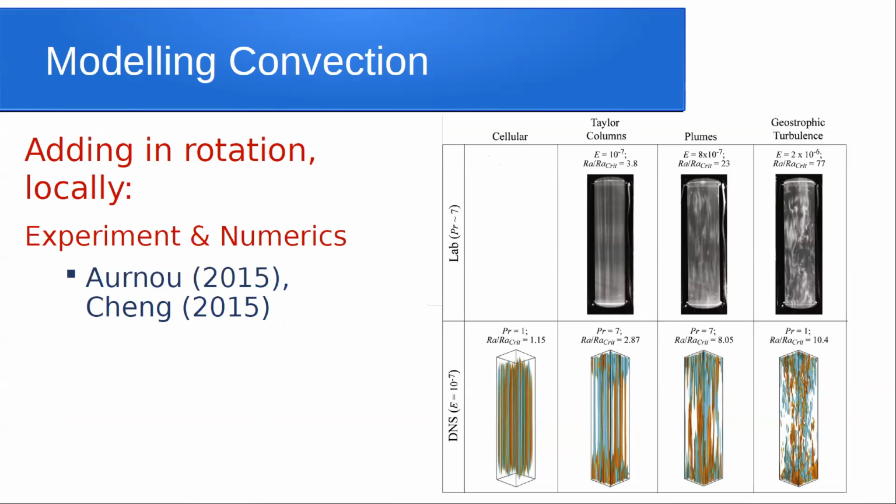So we're talking about Rayleigh-Benard convection in a box so far. What you're seeing here on the top are lab experiments. I don't remember what the substance was. Maybe it was water with particles in suspension, so you can actually see what the turbulent flows look like. And then you have DNS, direct numerical simulations, of a similar system. Basically what you see are different kinds of structures. In this first one, you have these fairly laminar structures. They form Taylor columns effectively, where you're in a geostrophic balance.